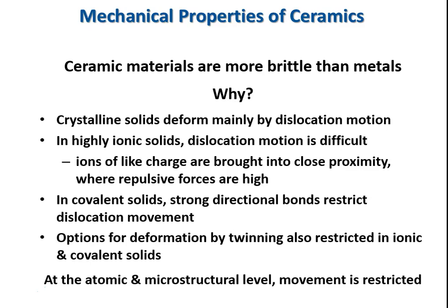Ceramics are either ionic solids or they're covalently bonded solids, and in ionic solids, to move a dislocation, sooner or later you have to bring cations in close proximity with other cations, because an ionic lattice, of course, has alternating positive and negative charges. Usually the cations being in the interstitial sites and the anions being on the lattice points, but a dislocation will eventually index everything over, and so you'll have like charges going into very close proximity. That has a very high repulsive force. So in order to get a dislocation to move, you have to overcome that force.